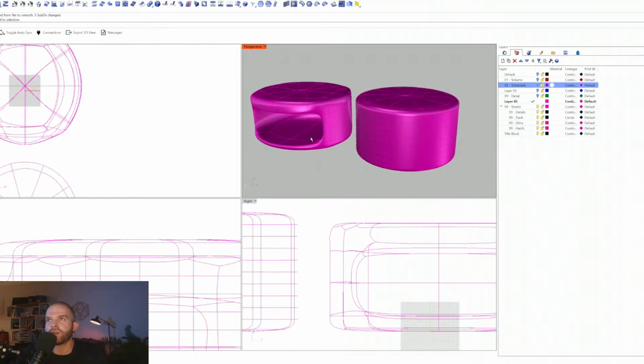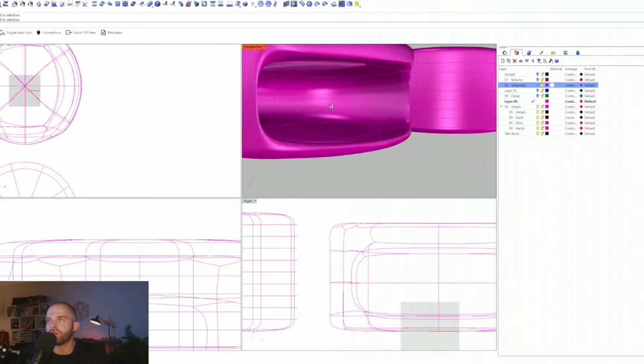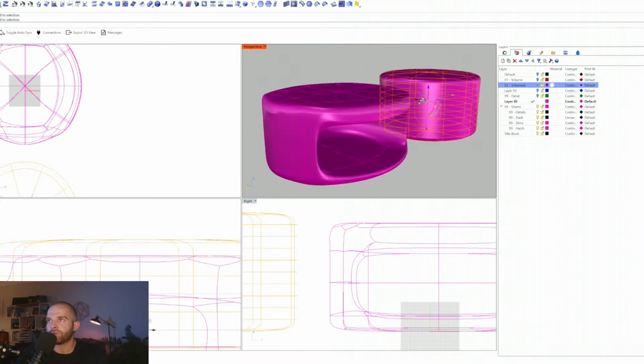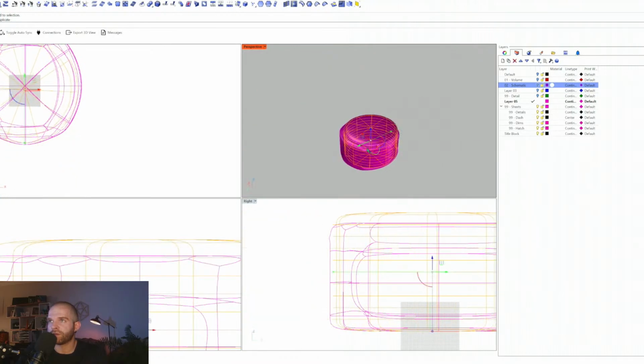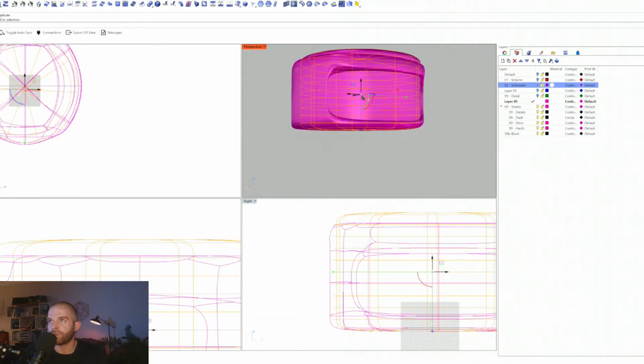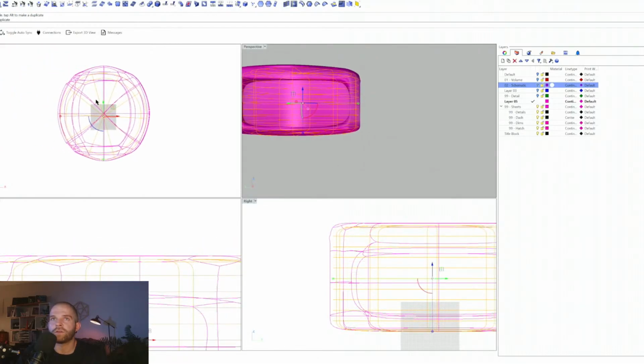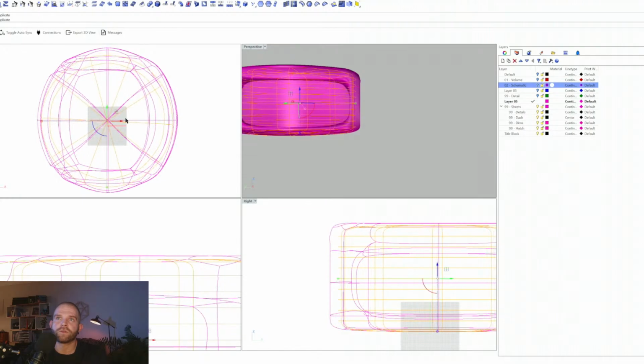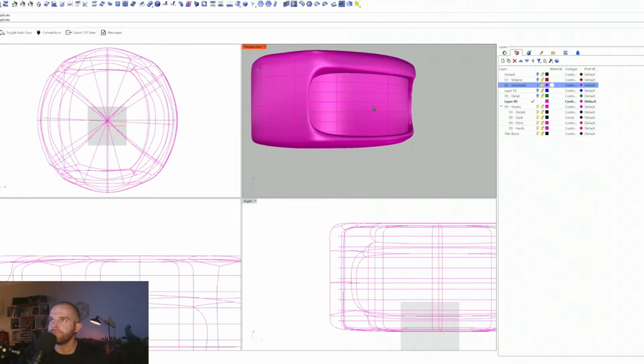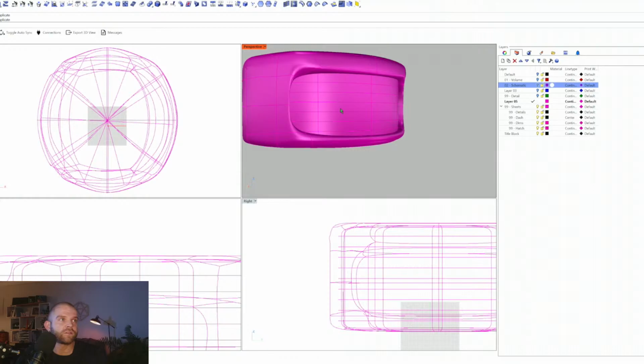But we could do a SubDOffset. So for example, let's say we want to bring back this original thing, or we want to use this to basically create our glass panels within this shape. I can lower this down. I'm just going to roughly put it into place. Cool. If that's going to be our glass, we could do SubDOffset to basically add some thickness to this piece.